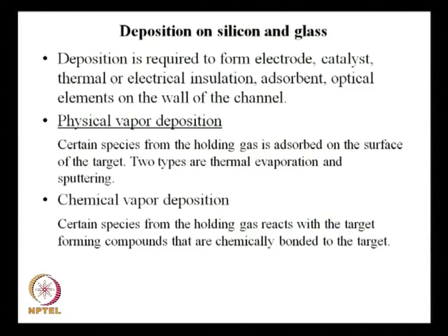The other deposition method is chemical vapor deposition. The short form is CVD, and it is again a very popular technique. Here certain species from the holding gas react with the target, forming compounds that are chemically bonded to the target. So, you have a chemical reaction happening, you have chemical vapor deposition, and when it is done just by a physical adsorption method, it would be physical vapor deposition.